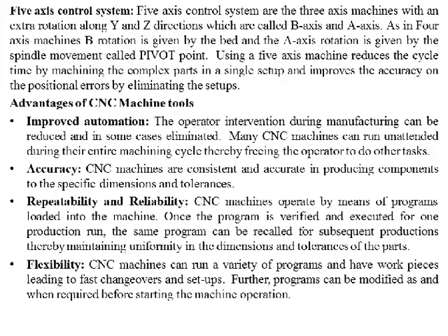So here the 5 different axes are X, Y, Z and B axis and A axis. So altogether we have 5 axes. This B axis will be along the Y direction and the A axis will be along the Z direction. Using this 5-axis machine will reduce the cycle time, so the time taken to produce any part will be reduced.